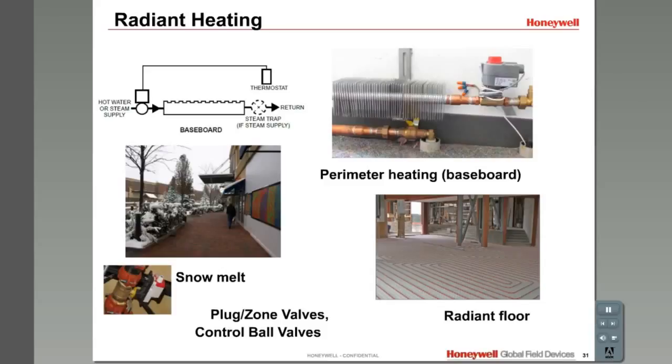Obviously, this water must not freeze, so it is mixed with glycol to lower the freezing point. In certain locations, radiant cooling may also be used, but it is critical that the surface, the floor perhaps, does not cool below the dew point and become wet and slippery. These applications may use ball valves, cartridge cage valves, and globe valves, or plug-style valves. The valves may have two-position actuators with or without spring return, although modulating actuators are also used.